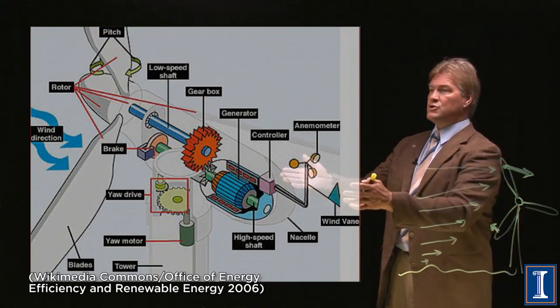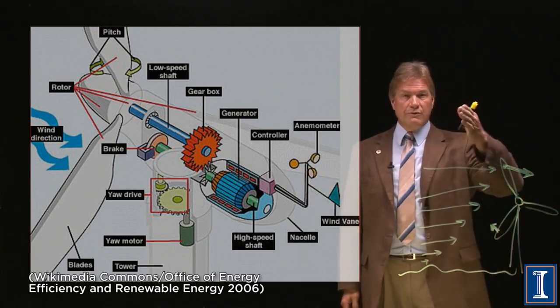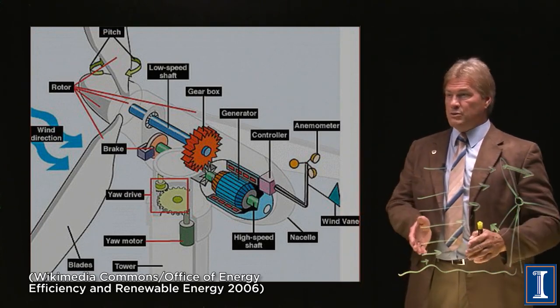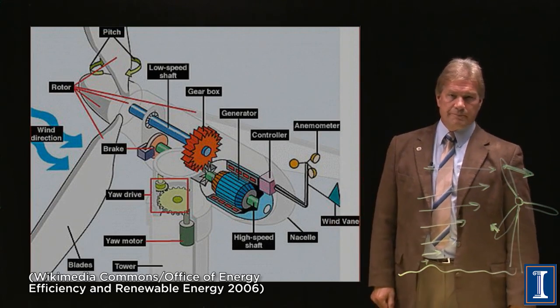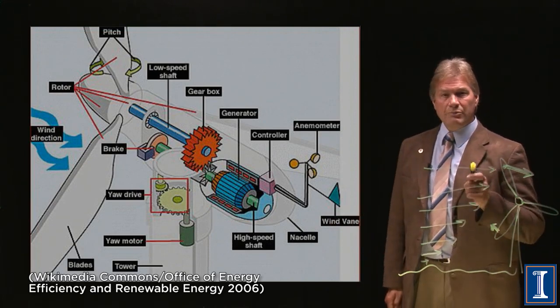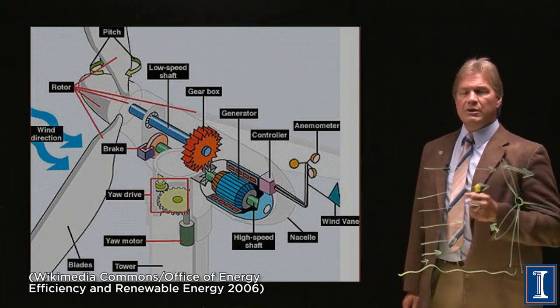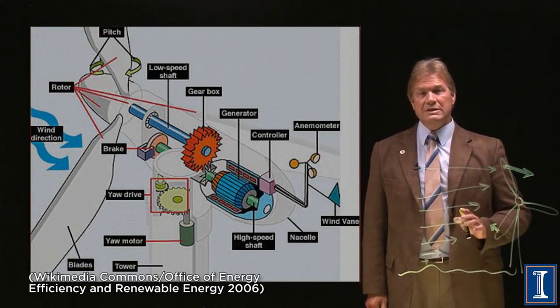And that's why the entire generator set is up in the air. The whole thing can swivel. If you tried to do this with gears and keep the heavy parts on the bottom, you'd wear them out for sure. But taking care of this inherent wind shear torque has been one of the greatest engineering challenges, which today has largely been solved.